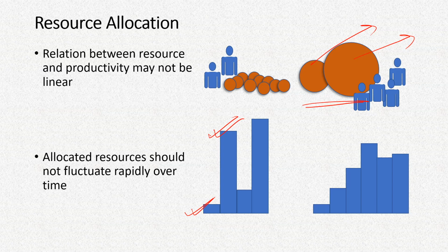Therefore it is advisable that you increase the labor force gradually, and when you decrease it, then also it has to be done gradually, because many of these laborers are not paid a salary but a daily wage. If they are called in for one day, then not called for the next 2 days, and again called the day after that, it becomes unreliable and they would not be willing to work with you if you are a contractor, and they will look somewhere else.